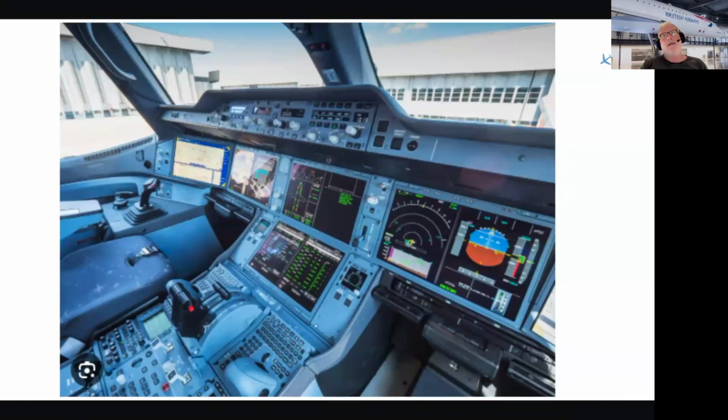And I'm talking, the display system is just one example of what Arinc is used for, and we'll see in a minute why. I just want to highlight here that Arinc 629 was patented by Boeing, specifically for the 777. They improved on Arinc 429, and although subsequent users, even Airbus now, use Arinc 629, every time Airbus uses Arinc 629, they have to pay royalties to Boeing because Boeing developed it and patented the 629 concept.